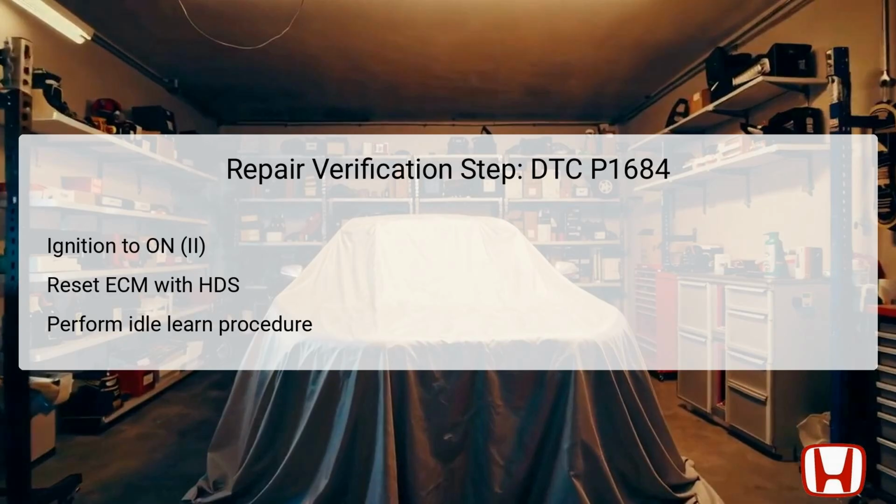Following the ECM reset, it is important to perform the idle learn procedure, which allows the ECM to adapt to the new or cleaned throttle body settings. This process is essential for the vehicle to operate smoothly, especially after any repairs or replacements have been executed. After completing these steps, turn the ignition to lock 0 once again and wait 10 seconds before returning to on 2 to check for any pending or confirmed DTCs, verifying the success of the repair.